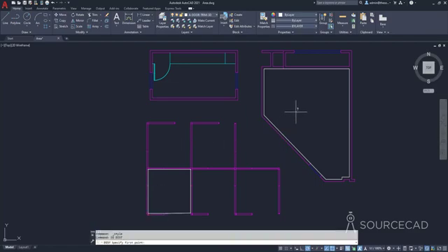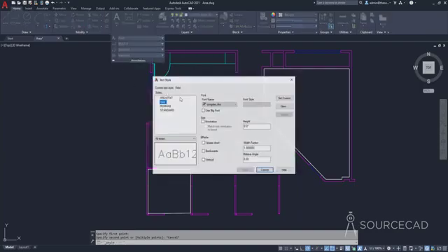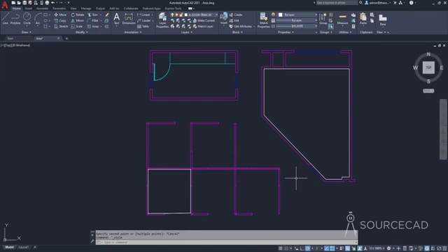I'll check the height simply by clicking on two random points, and it looks like a text size of approximately 10 inch is going to look good here, so I'll be using 10 inch as the text height. Alright, now I've got the text height. I'll go back to this text, the field text, and height I'll set it as 10 inch. Apply and close. There we are. We are ready to use the field.